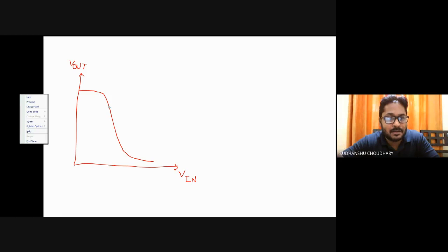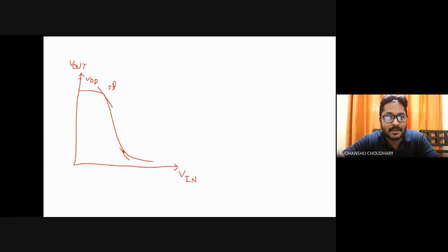In this case we have an inverter, so the gain of this inverter will decide these levels. Let us say my VDD lies somewhere over here. And my VOH and all these levels can be found by the approach where you find a point on the VTC where the slope is -1. This technique we had already seen.